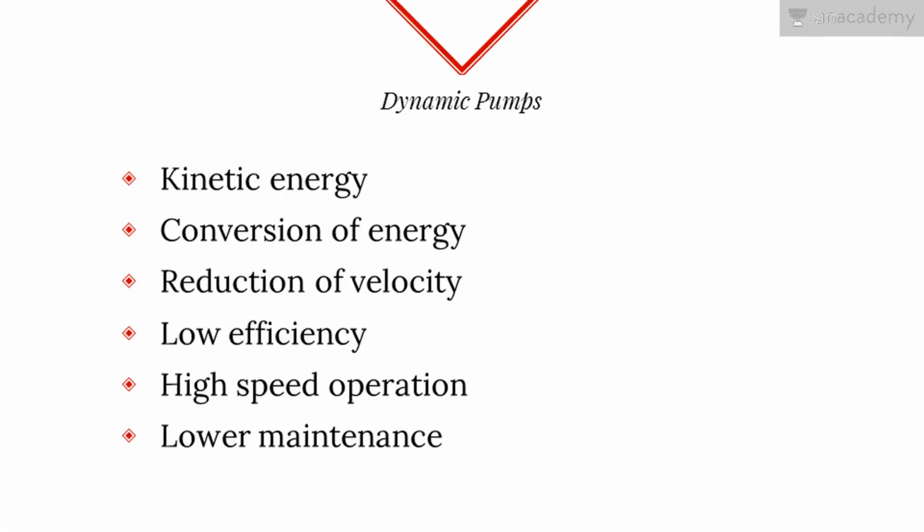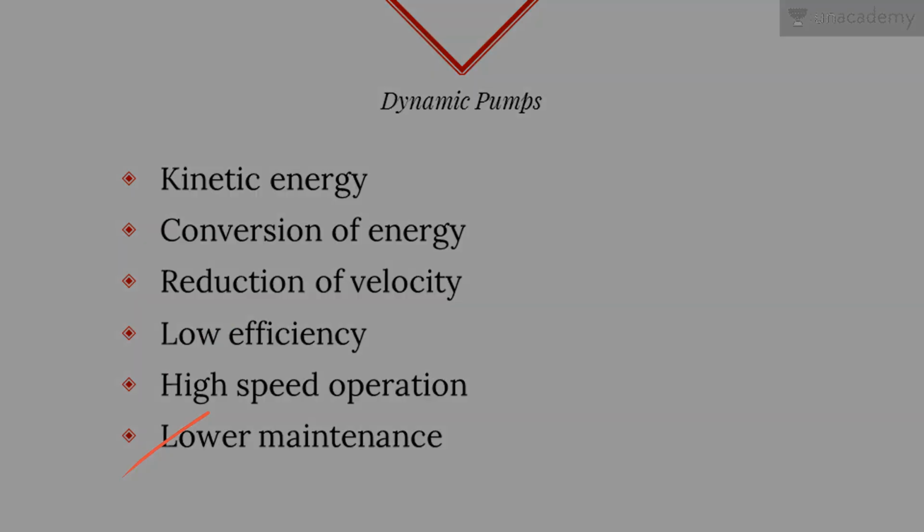Let's go into dynamic pumps. They are a type of velocity pump in which kinetic energy is added to the fluid by increasing the flow velocity. This increase in energy is converted to a gain in potential energy or pressure when the velocity is reduced prior to or as the flow exits from the discharge. These pumps are generally lower in efficiency than positive displacement pumps. However, they do operate at relatively high speeds and they have significantly lower maintenance requirements.